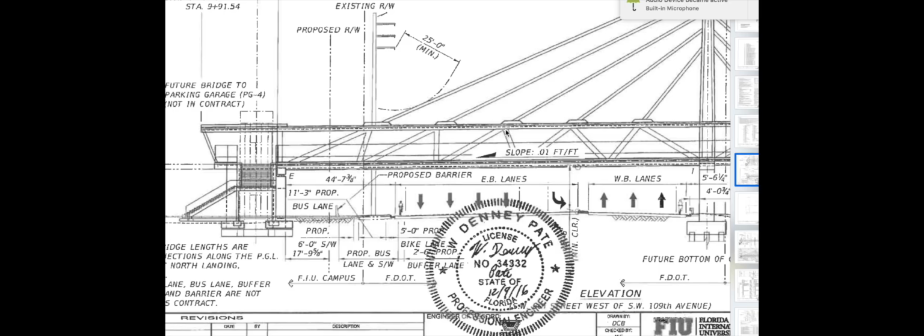This is your weakest point on the joints. This is what keeps this from sagging. All of these joints in the truss plate system, locking it in, making all the truss systems work as one piece. You can't remove one truss plate, or you've just screwed everything. Now, I digressed on truss plates.